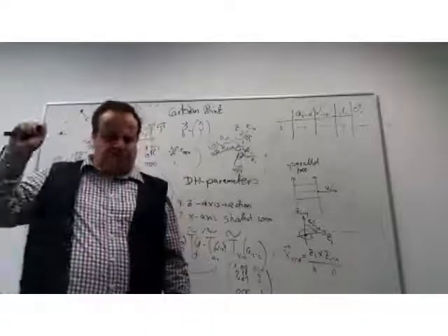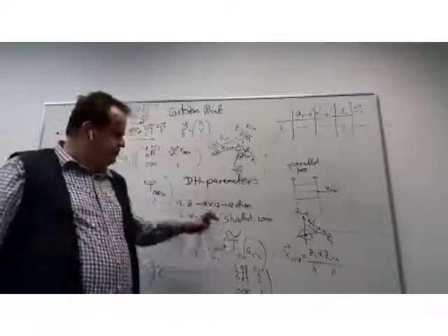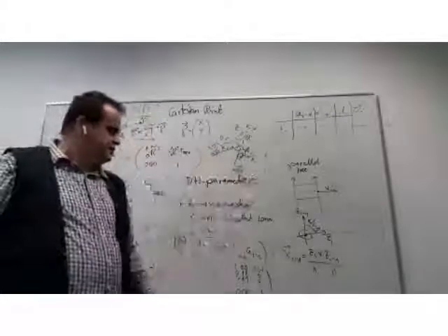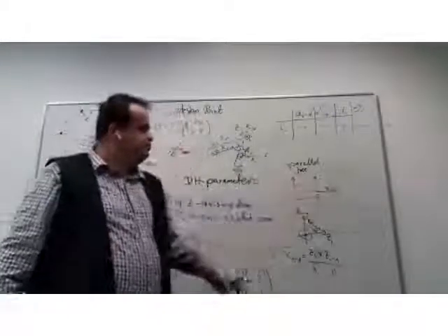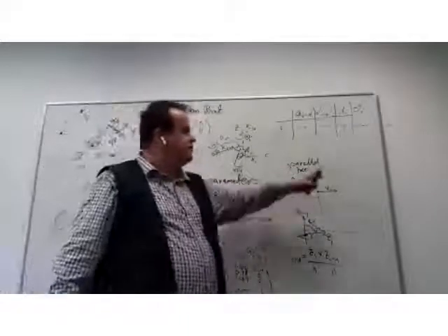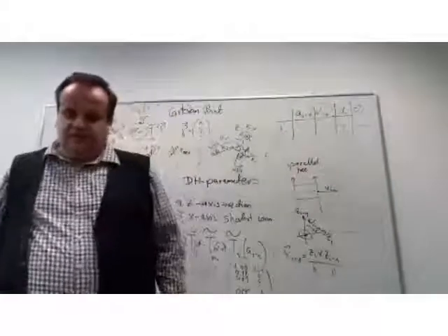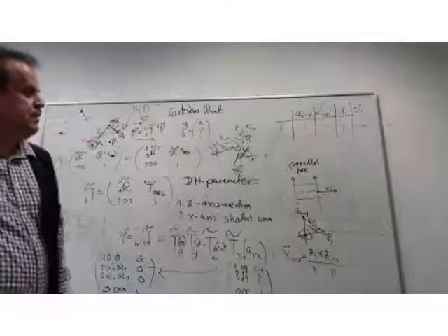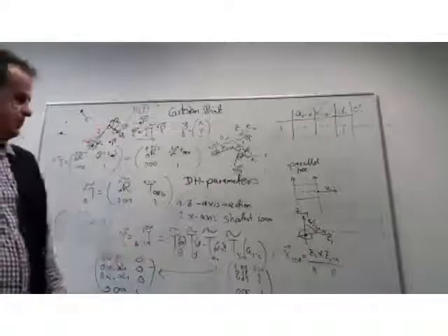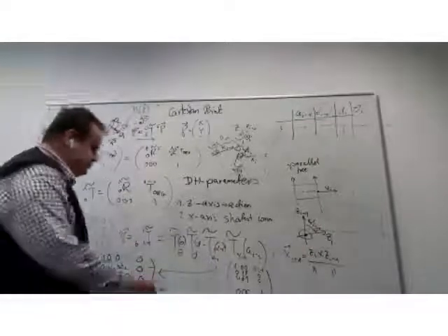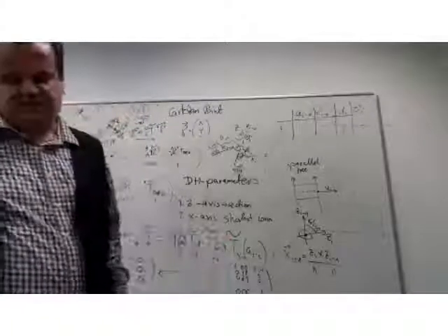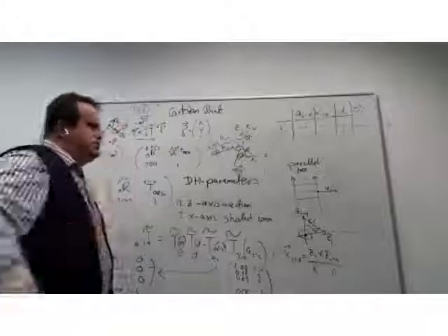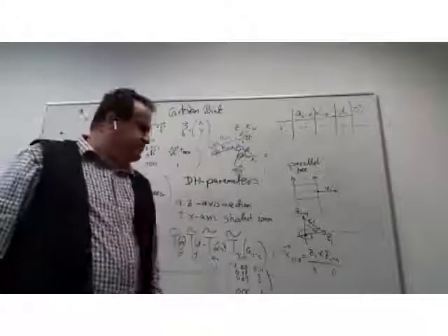Then find the x-axis using the strategy of shortest connection, with a free choice of placement. You see now why I aligned it to the next one. This gives me a d equal to 0 in the table, and d equal to 0 actually makes this an identity matrix, so it simplifies the forms with many zeros in each table.